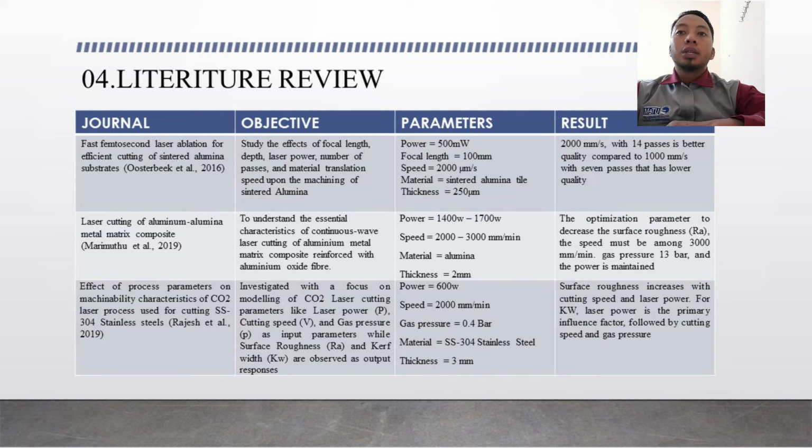The parameter used is power 500 mW. The focal length is 100 mm. The speed is 2000 micrometer per second, and the material is sintered alumina tape with 250 micrometer. And the result is 2000 millimeter per second with 14 pass is better quality compared to 1000 millimeter per second with 7 pass that has a lower quality.